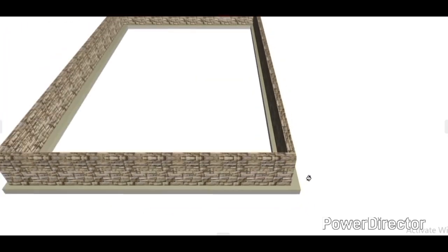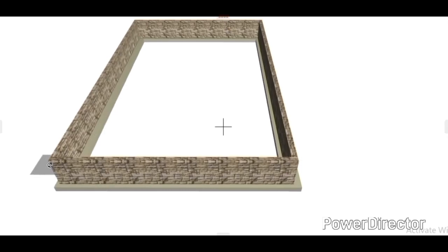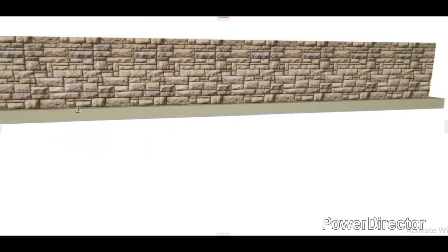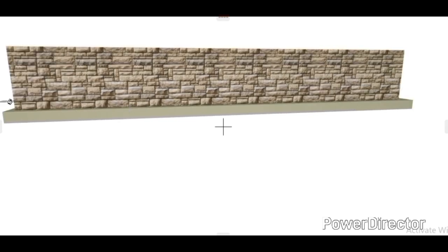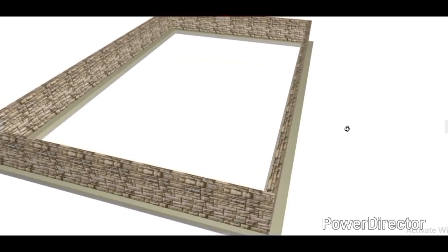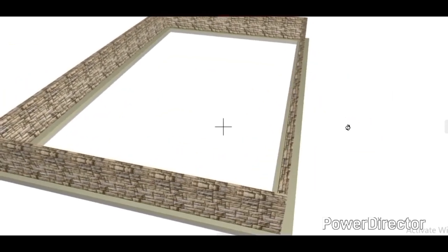So the width was from this external dimension to this external dimension of this wall, 8,000. Now the 8,000, if you add these two spreads of 200 this side and 200 this side, will make 8,400. So that is how the spread is being added to the dimensions.